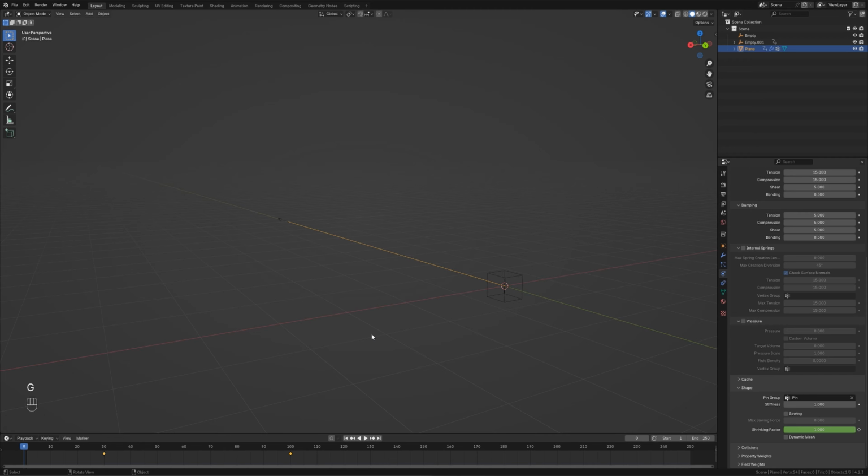And here's where the initial 10 meter length comes into play. Since the rope starts at 10 meters and the hook moves to 50 meters, the cable needs to be 5 times longer. A shrinking factor of around -4 gives us that extension. So as the empty moves away, the rope extends along it.